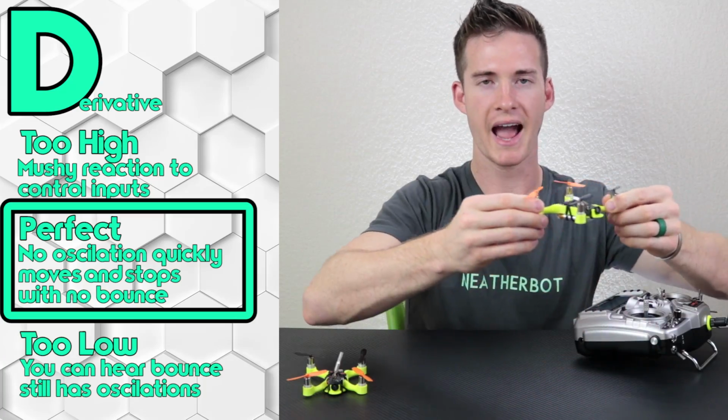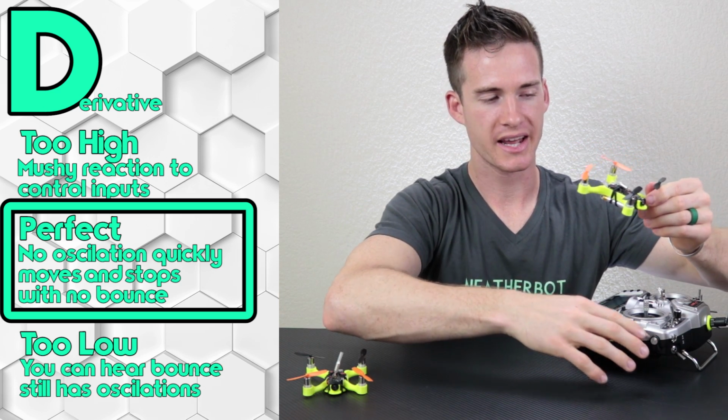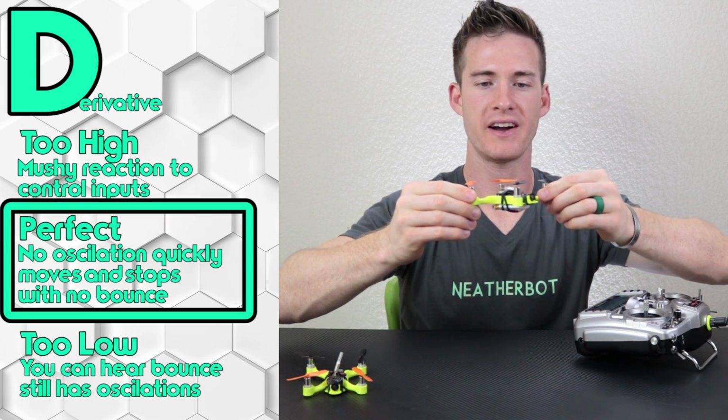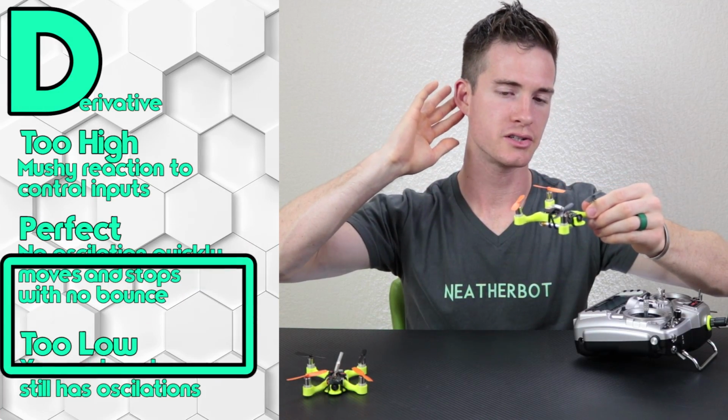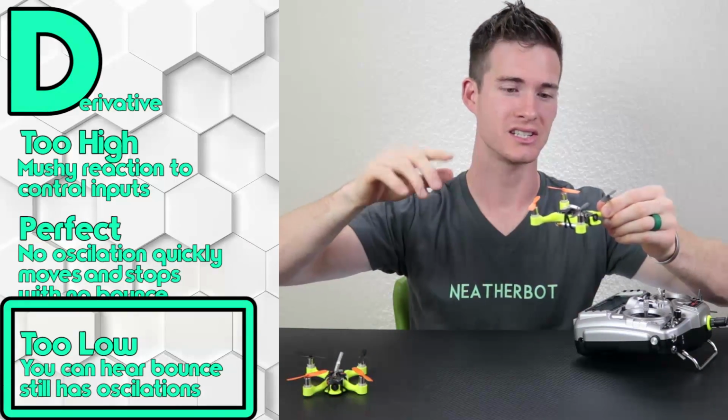You can stop adding D. If you want to, you can tweak it a little bit, but D is pretty easy to find because it's very noticeable whenever you stop getting those oscillations. Use your ears too. It's easier to actually hear the oscillations than to see them.